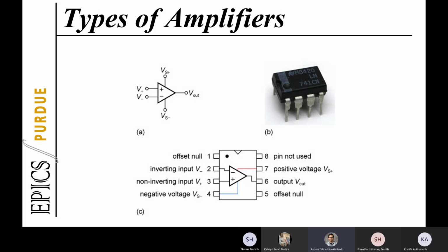If you're trying to drive a motor that needs 1 amp to work, most likely the Arduino might not be a good option since, if I remember correctly, the output of the pins is 500 milliamps max. So you might not be able to provide enough current through the Arduino, but depending on your application, you might or might not be able to use that as a viable power supply.